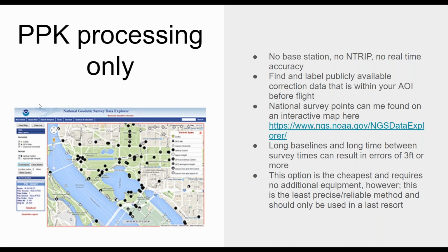Now, long base times between survey data points and sloppy marking can result in large errors with no way of knowing and no backup, rendering entire data sets useless. This method is a great way to introduce errors into your data set with human error. You may have awesome data from your GNSS base station and rover. However, if you go into your data set in post and inaccurately mark the data points with your GNSS data, it's just like you didn't even take the data yourself.